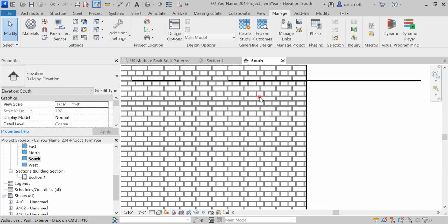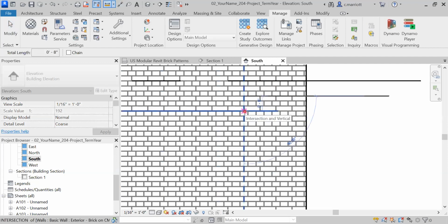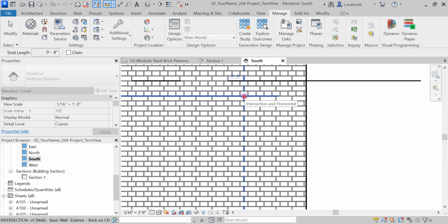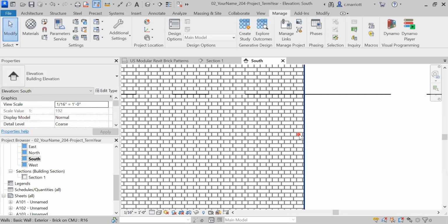So they're large, so I'm going to double check and make sure I chose the correct brick size. And you also want 3 courses vertically to add up to 8 inches. So this one checks out in that respect, but I'm going to double check this and I'll choose a different, yeah, that's 8 inches. Okay. I'm not sure what I had clicked to. So the stretcher should be 8 inches and 3 courses should also equal 8 inches.